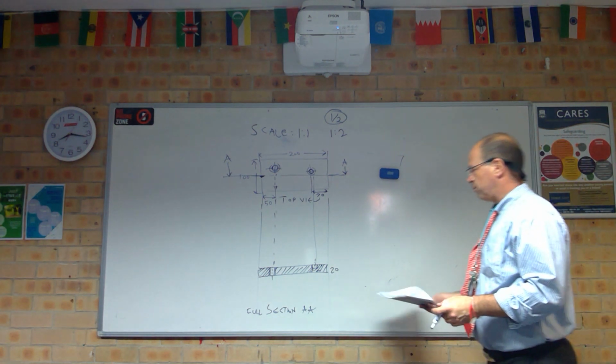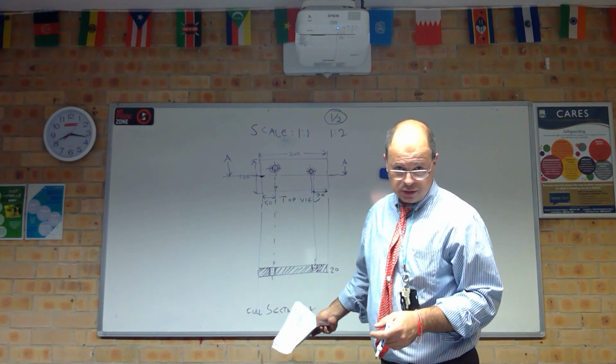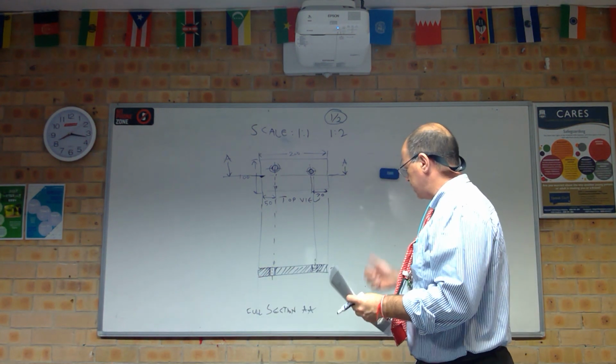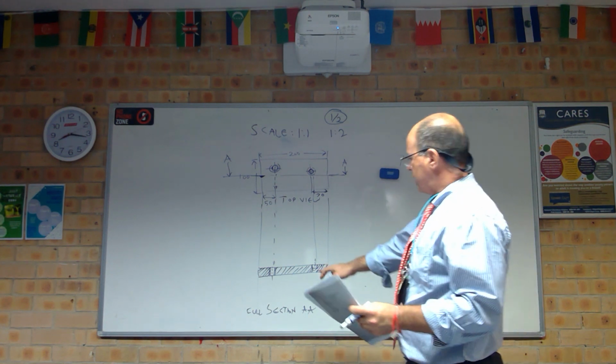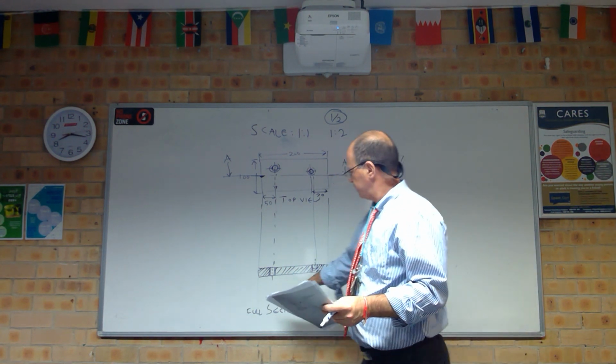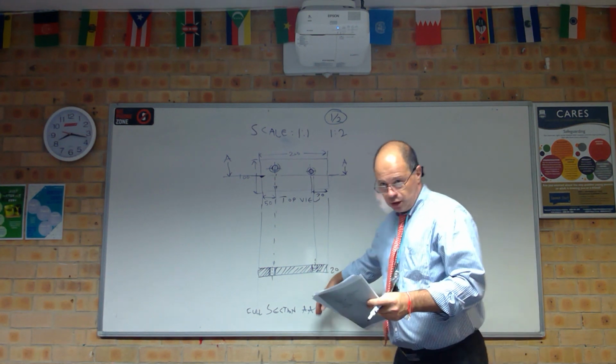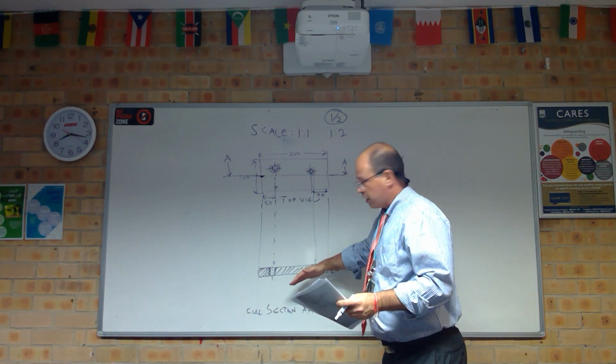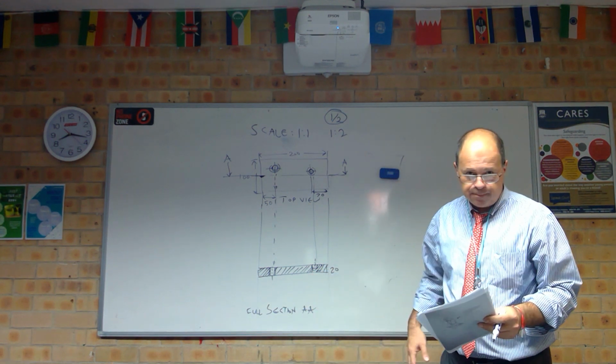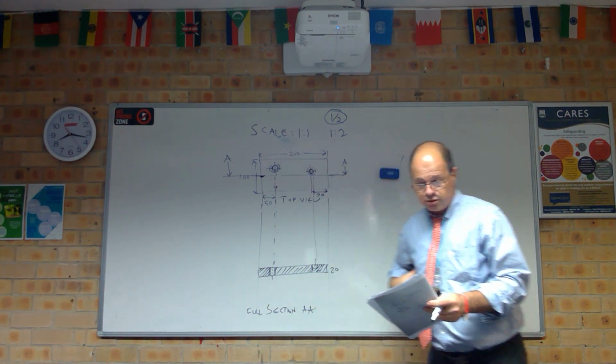Okay, so that is a sectioned view of that thing. You're practicing drawing thread lines. You hatch over your thread lines because there's no bolts in here. And same deal over here. And you practice doing a blind hole. You've done guidelines coming down from your top diagram. You're following instructions on how to do this.